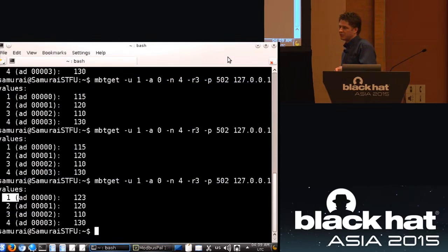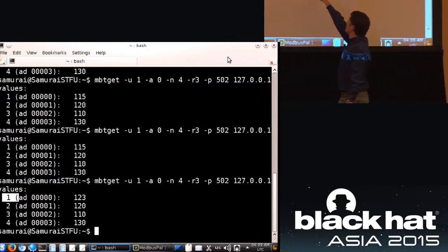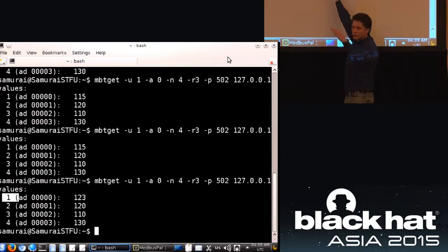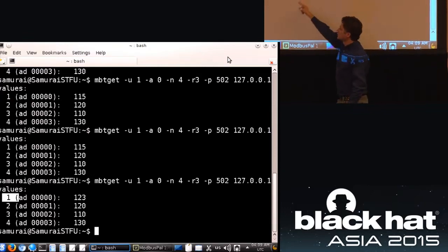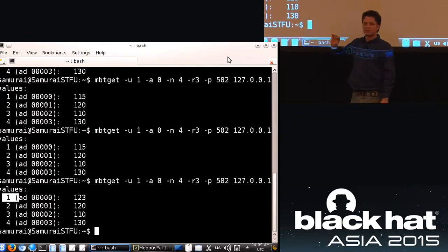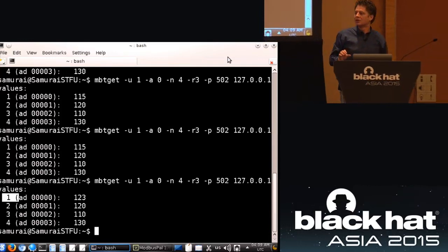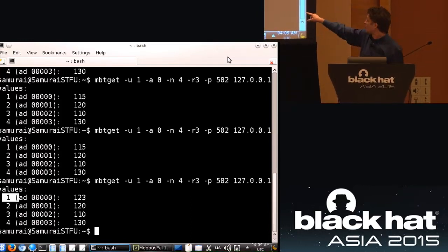Here's the other thing to it. Inside of Modbus, I'm saying read address 0, and I want to read 4 words or 4 different address values. Okay? So I read 1, 2, 3, and 4. So I read all that information. Do you guys see the tags in there? Do you see the names? Do you see the word input voltage, or output voltage? Okay?